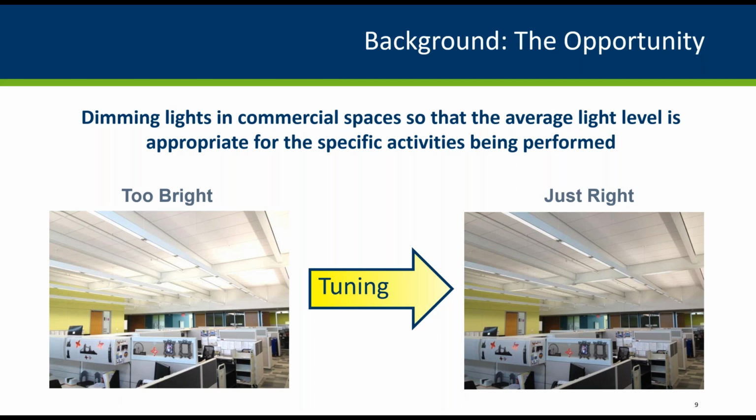In some instances, a lighting designer may not know what activity will be performed in a space. This could potentially be improved by a more integrated design strategy, or perhaps no formal lighting design occurred, particularly in the case of one-for-one LED retrofits. A contractor may simply install lighting based on rules of thumb or based on what they've done on previous projects. Or a lighting system may not have been commissioned, meaning the installation may not be consistent with the design intent.